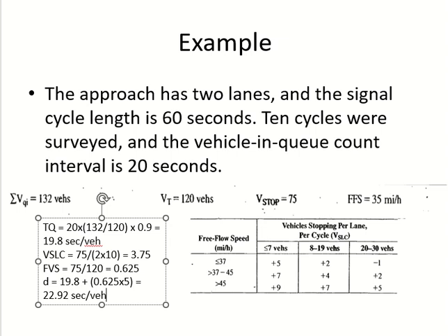But it's not matching because he is counting vehicles in the queue, whether he counted them before or not. So maybe the signal timing is 30 seconds, let's say. The red is 30 seconds. So in 20 seconds, he will find some vehicles which are already there. He's counting after 20 seconds, right? So maybe the signal was red, after 20 seconds it is still red. So he will count that vehicle again, which was already there. So there is multiple counting for this guy, but not for the other guy.